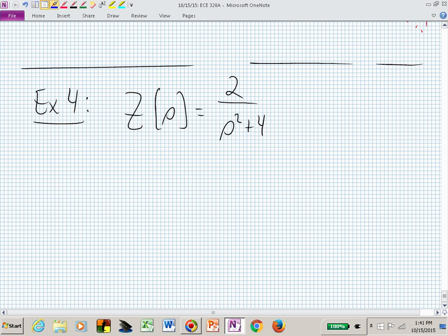You're now immediately starting to look at s times capital Z of s, and saying, okay, where are the poles that I have? And I might give this to you on the test. I might give you a quadratic. So now you're interested in this. And what do you want? In order to apply the final value theorem, you need negative real parts, don't you?